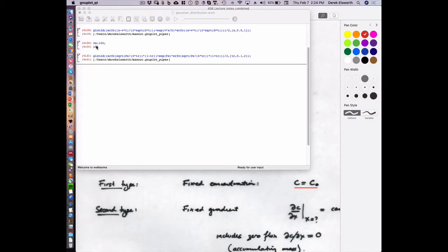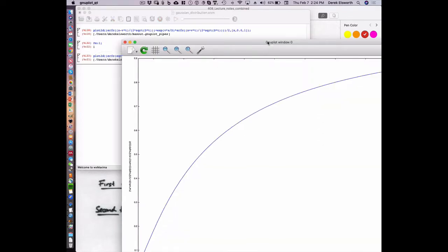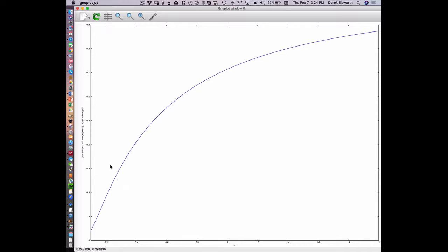If we make the Peclet number smaller, say 1, then all of a sudden the 50% concentration is here. This is now 0.9 instead of 1. And so 50% concentration occurs at 0.45 pore volumes, not 0.5 pore volumes.